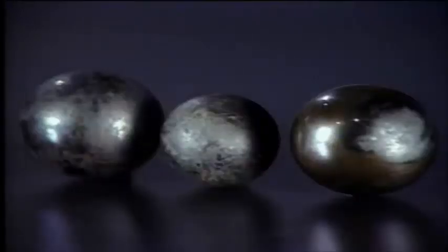More severe oxidation produces carbon deposits. Both varnish and carbon deposits can greatly increase friction on bearings and other machine parts and keep them from operating freely. Carbon deposits can also collect in lubricants and form sludge.